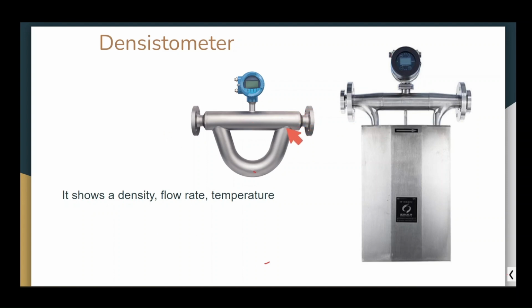The mechanism, the principle of this densitometer: when slurry goes through this pipe from the densitometer, a Coriolis force occurs, which transforms to slurry fluctuations with different frequency, and we can transform this frequency to slurry density level.